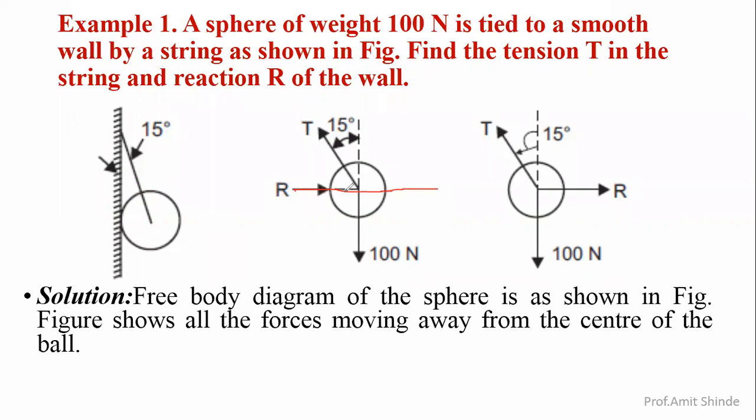We may put this R over here, or over here, anywhere on the same line of action according to the law of transmissibility of force. Therefore, this resultant R we are showing over here like this, and the effect will be the same according to the law of transmissibility. The force we may replace anywhere over the same line of action with the same magnitude and same direction. That's why we are representing this figure like this. This R is replaced over this location according to the law of transmissibility.